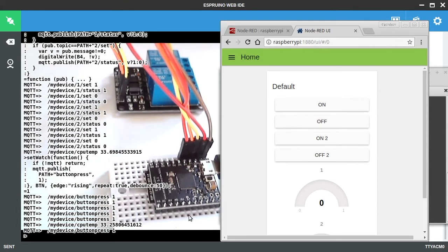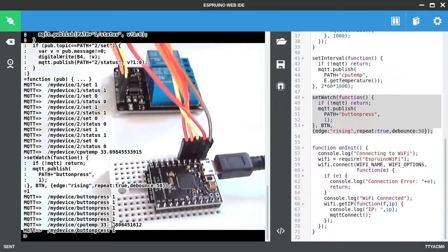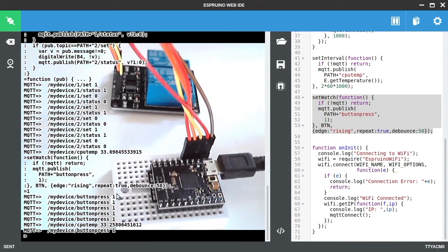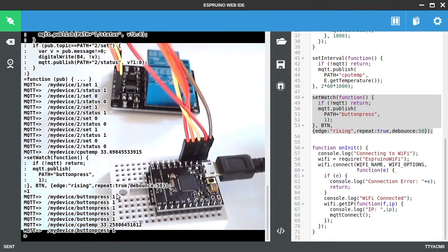And we can, like we had with the CPU temp here, we can even log that just by dragging it onto a chart. And that's it. You can have as many of these as you want. You can also use Puck.js and a bit of software called Espruino Hub that will help to convert Bluetooth Low Energy to MQTT, and you can wire things up with that.